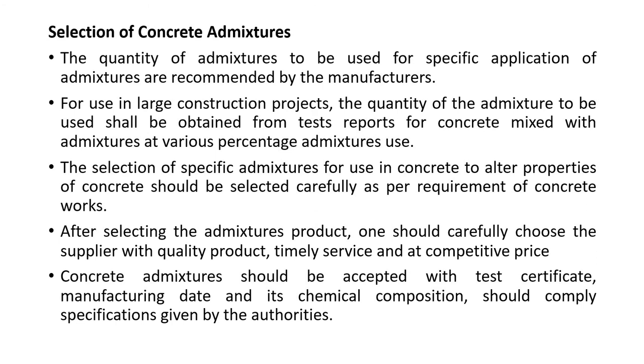After selecting the admixtures, one should carefully choose the supplier with a quality product, timely service, and competitive price. Concrete admixtures should be accepted with a test certificate, manufacturing date, and its chemical composition should comply with specifications given by the authorities.